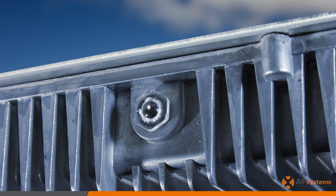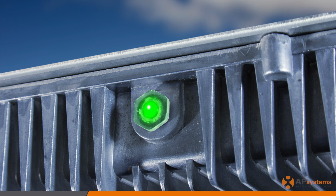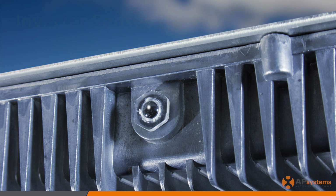If the LED is flashing green quickly, every 2 seconds, the inverter is producing power but not communicating with the ECU. This is a normal condition if you have not installed an ECU as part of the system design. Note that the green LED actually means that the inverter is sensing the grid within the set of AC parameters that have been programmed into the inverters.